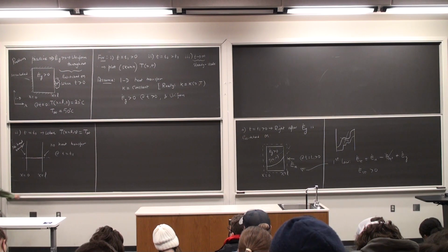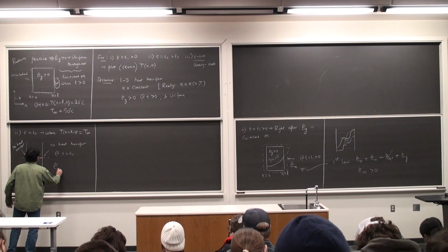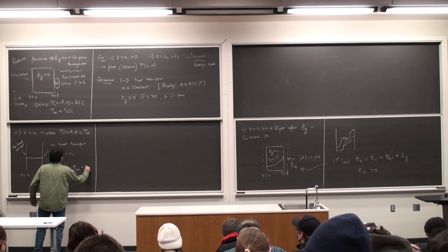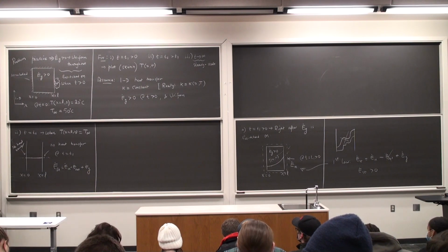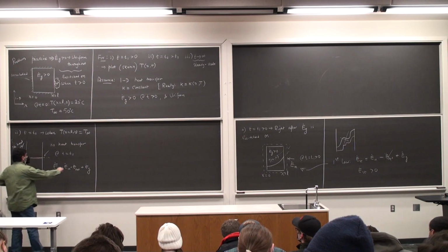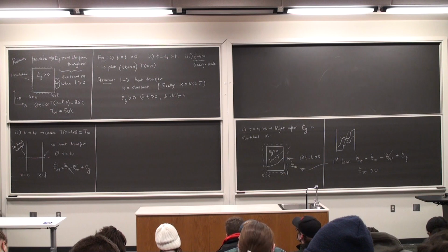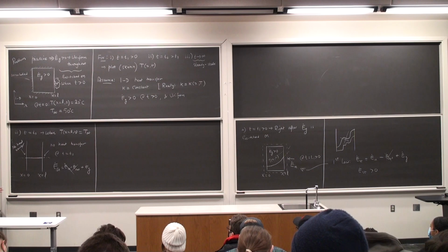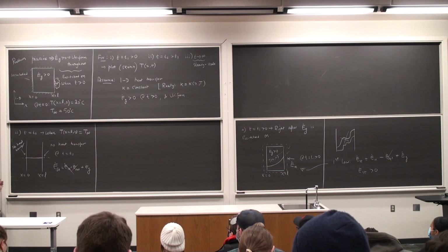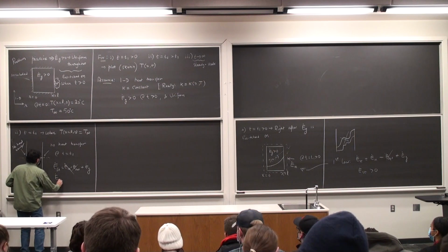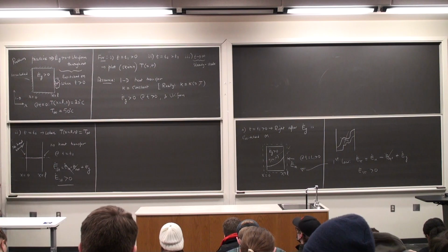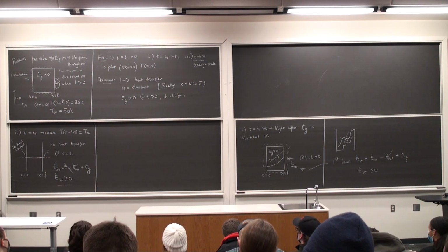What about my first law? E dot in, E dot out, E dot generated. At this instant in time, there is no heat coming in and no heat going out, so E dot in and E dot out are both 0. But E dot G is still non-zero and positive, so the temperature of this wall is still increasing with time. E dot stored is still greater than 0. Then we go to steady state.